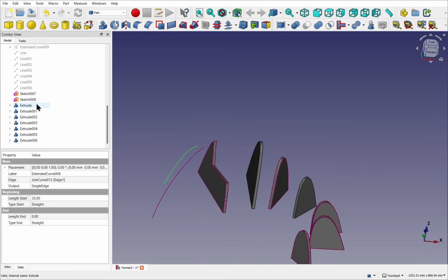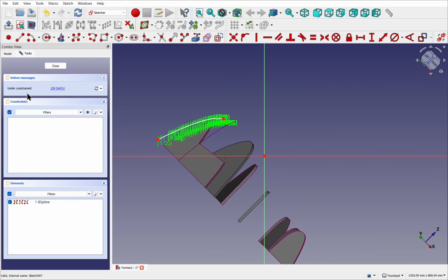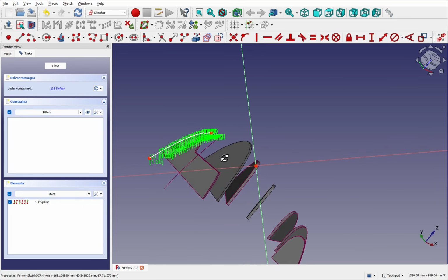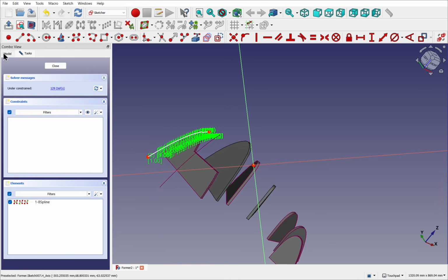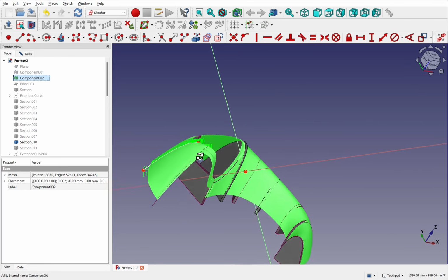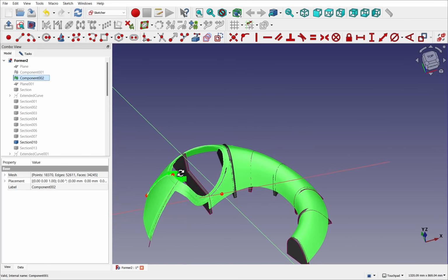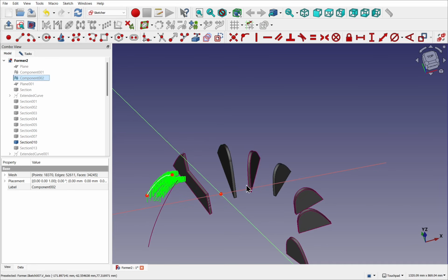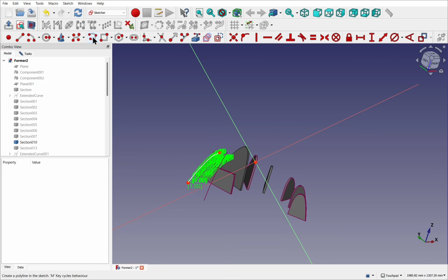Then we have this one. I've selected that, and what have we got selected? So it's at the top here, this extend curve. So I'm going to select that and press the space bar. Still visible for this one. We'll click that. And we need to do something with this, because if we come back and have a look, this is this part here. So we just need to make a simple extension of this going down and across. Press the spacebar again to hide that mesh and use the polyline.